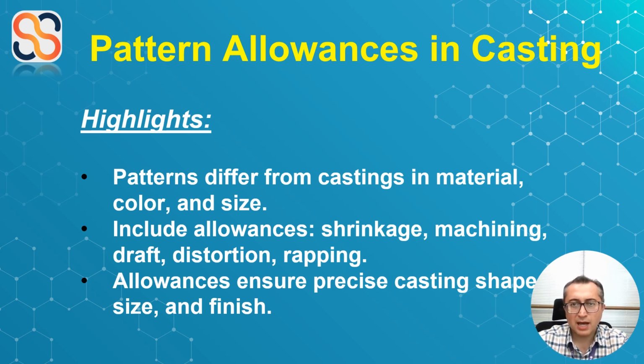Patterns may also have core prints. These projections allow space for the core, which helps create internal cavities or hollow sections in the casting. With core prints, we ensure the core sits perfectly in place, aligning with the other mold features.